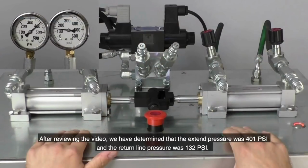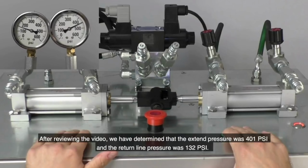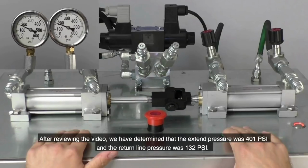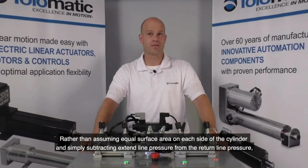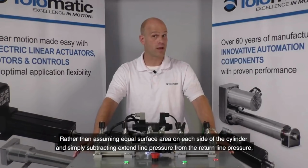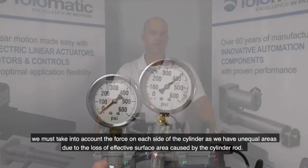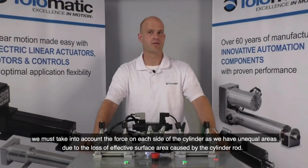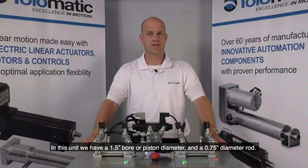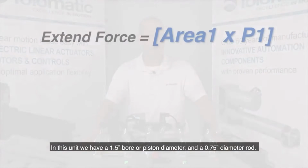After reviewing the video, we have determined that the extend pressure was 401 psi and the return line pressure was 132 psi. Rather than assuming equal surface area on each side of the cylinder and simply subtracting extend pressure from return line pressure, we must take into account the force on each side of the cylinder, as we have unequal areas due to the loss of effective surface area caused by the presence of a cylinder rod. In this instance, we have a 1.5 inch bore or piston diameter and a 3/4 inch diameter piston rod.